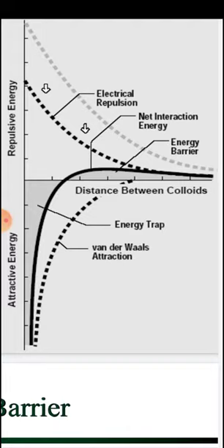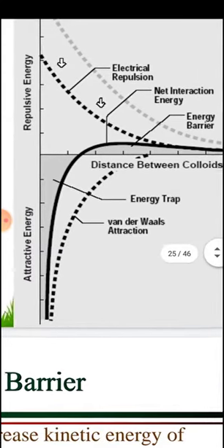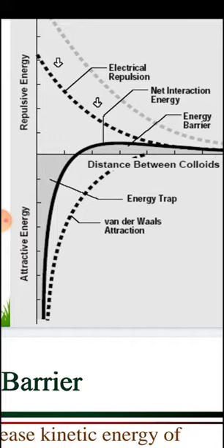Because of that increased ionic concentration, the ions are much more closely bound with the fixed layer, and thus the thickness of the diffused layer has reduced in this case. So this is the requirement for destabilizing the colloidal particles. If we want to destabilize the colloidal particles, we must have high ionic concentration and higher ionic strength, because of which we will have a reduced diffused layer.